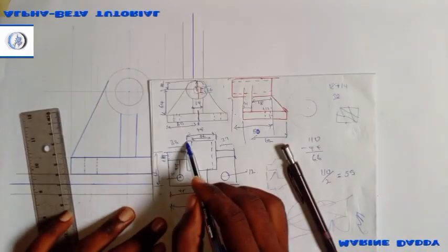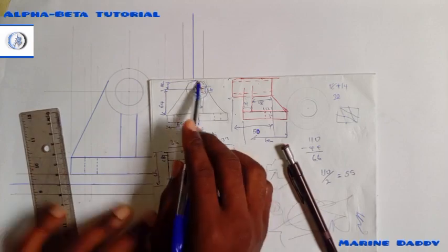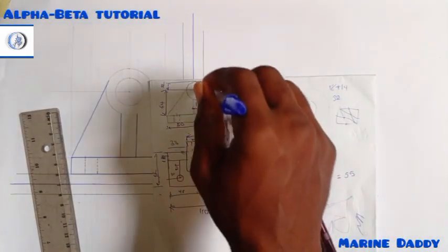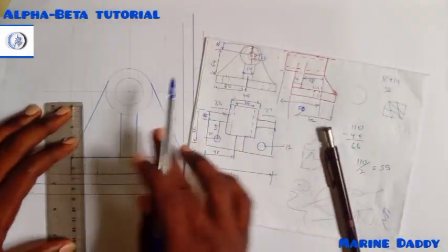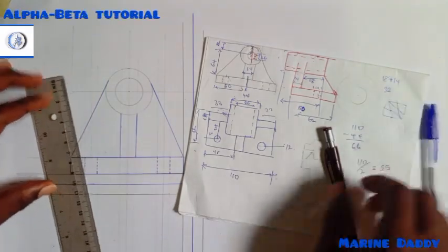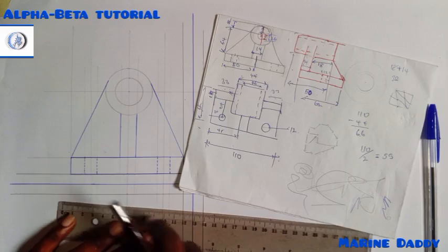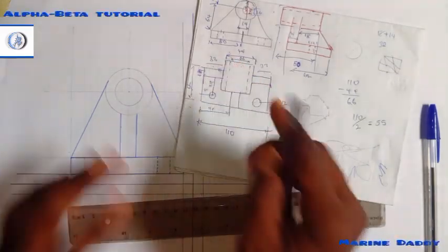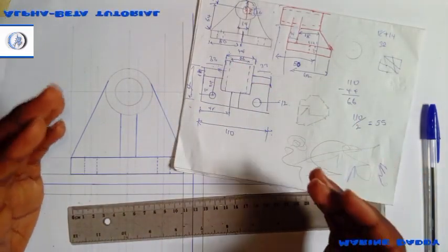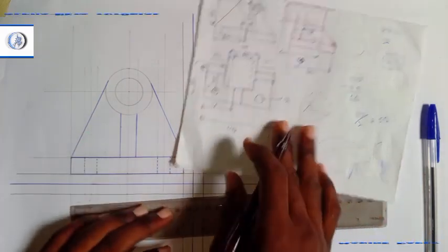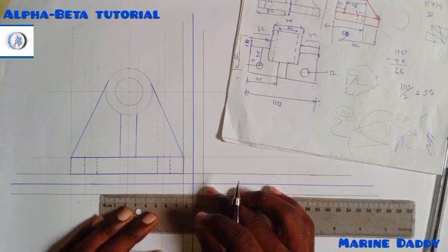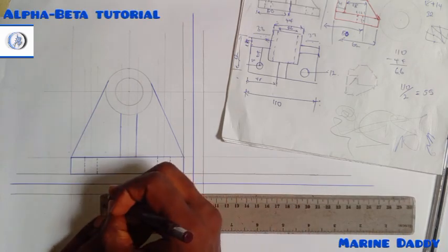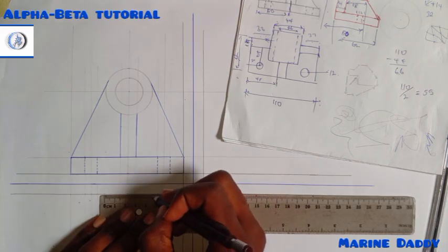This part is like this cylinder. You're looking at this cylinder from the top and seeing from the top, what you see is a rectangular shape, right? So I just have to take note from the middle. It is located at the middle. And the first one, like I said earlier, the diameter of the circular part is 44, the other one is 26. So that's 22 to the right, 22 to the left, 22, 44.